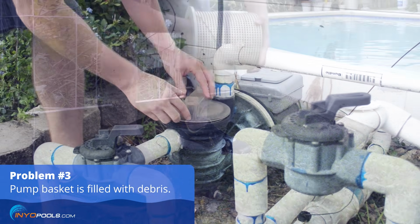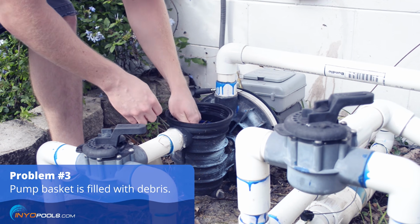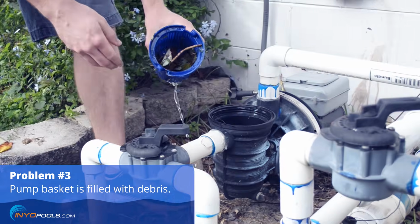Another basket to check is in the pump strainer. Like the skimmer basket, a full pump basket will decrease the flow to the pump. Again, empty any debris that's been collected in the pump basket.